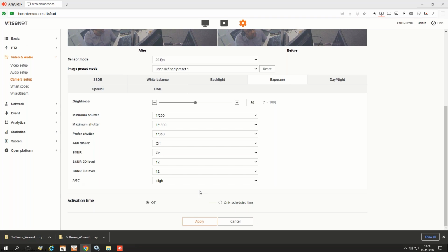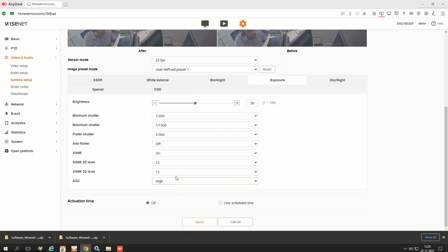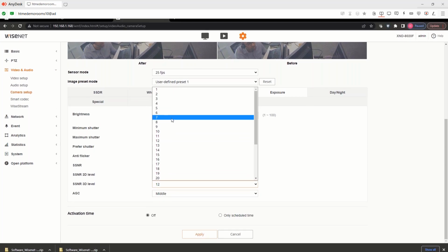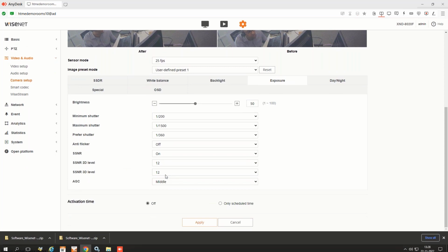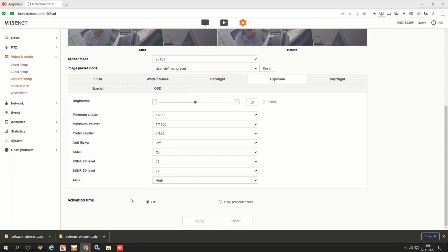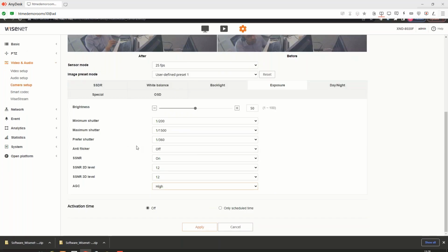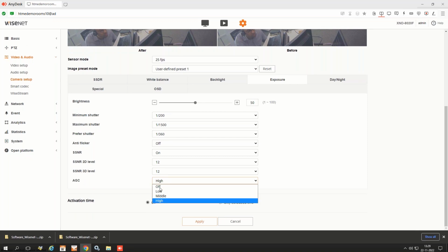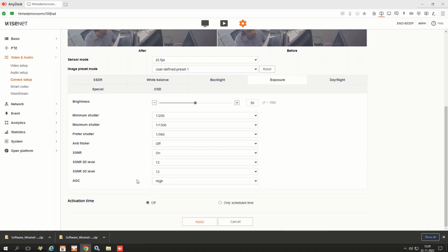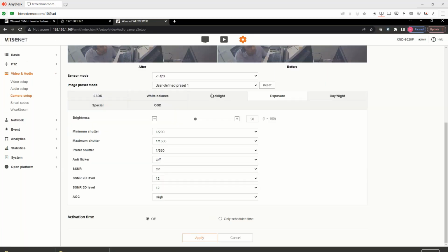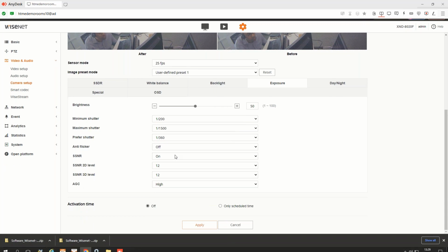Okay, so you can try to reduce to medium, everything to medium. Right now it's all around higher level, maybe 4 5 like that. So try to reduce this. Now when you make it high, yes, overall image will look very good, but your objective is to capture the number plate. So in those situations, try to make this lower. Extra processing, try to reduce. Okay, all this is probably with the number plate manual, you may find it, but I'm not 100% sure. So this is the most common steps that we generally do.